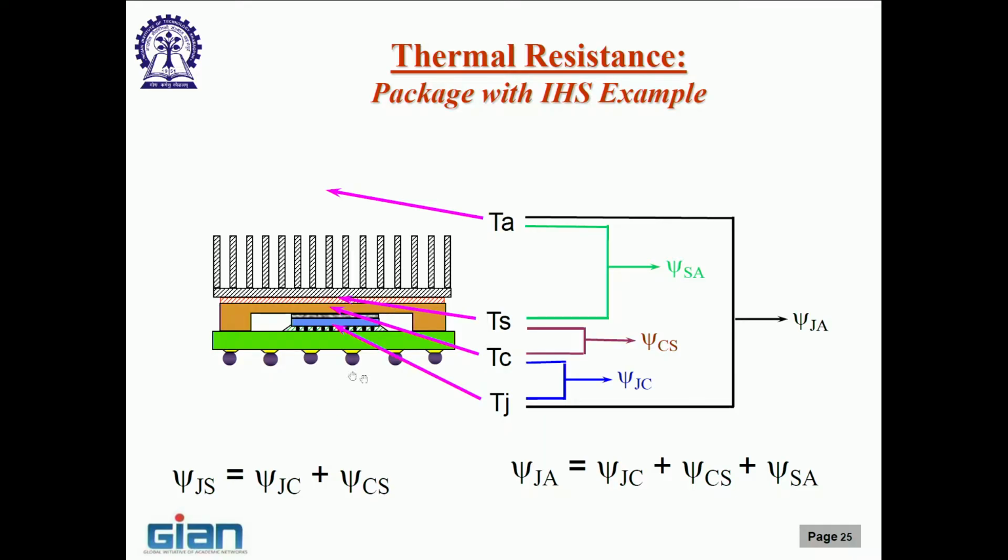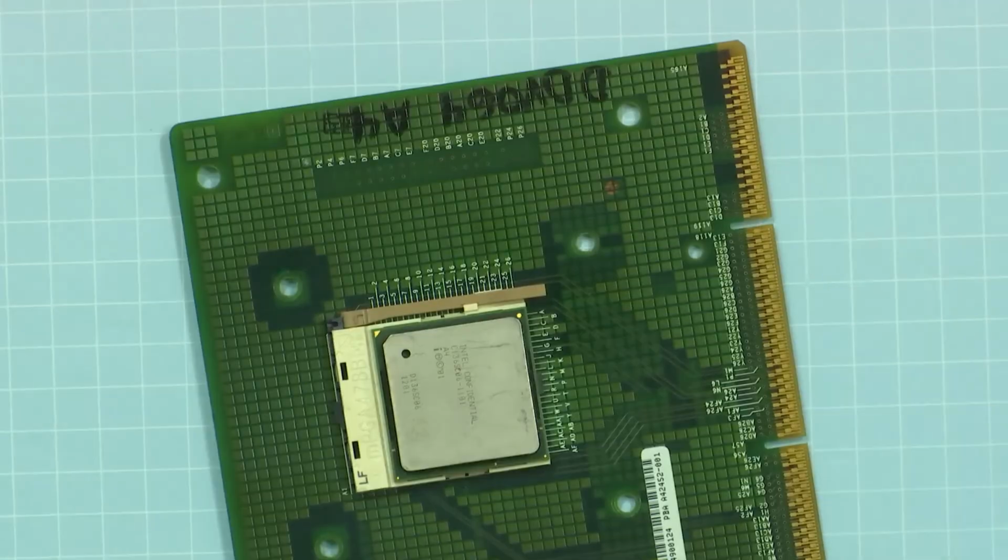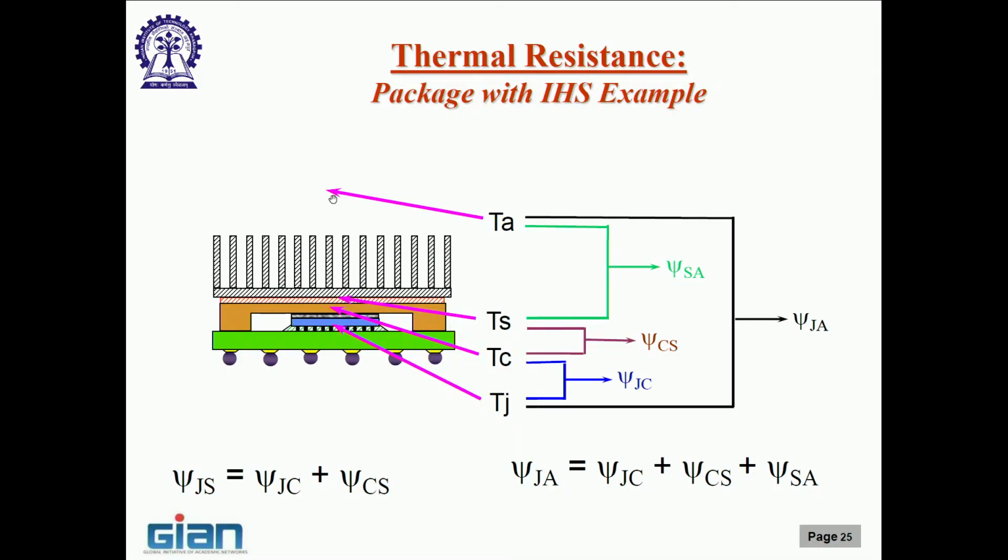few other, you have first of all two thermal interface materials. What are the different temperatures we are concerned about? Theta junction Tj, Tc is theta case, which is on top of this. Okay. Then Ts, the heat sink, and ambient. Why? Because I have a junction to case which includes the resistance to the silicon, the resistance to the first interface material, and a little bit of resistance and the resistance through this integrated heat spreader, which by the way is the conduction resistance plus the spreading resistance in light of the discussion we just had.